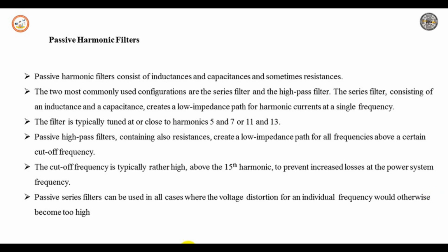Mitigation equipment based on power electronics converters has a high potential to improve the power quality, and static var compensators and STATCOMs have been successfully used to mitigate voltage fluctuation. Such converters can be installed at a central location in the system, for example to limit voltage fluctuation in the weaker part of the transmission grid close to the source of voltage fluctuations like wind turbines.